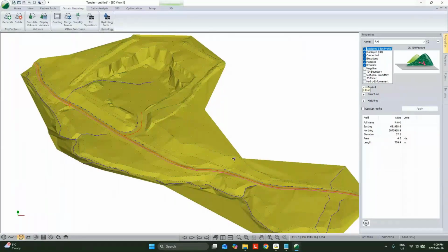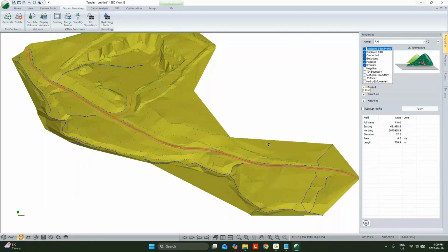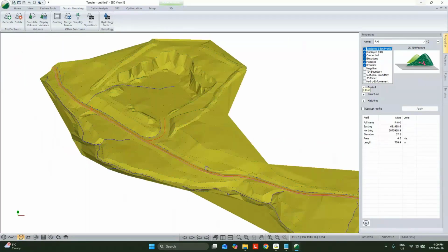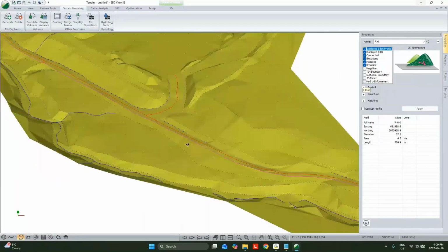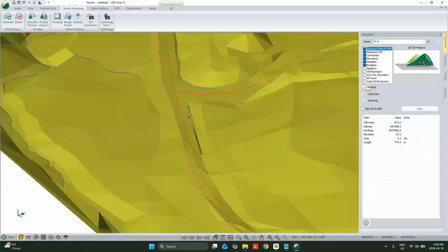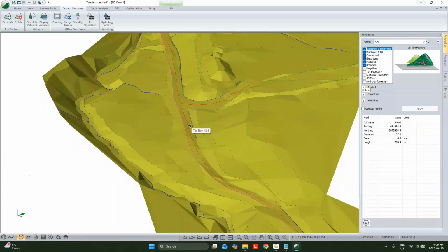One, we could totally just dump this right into LiDAR data and we'd have lines with the same information. Now, oftentimes that's not desirable. It gets a little funky, particularly in things like our ditches. The LiDAR data may have points here that are just poorly classified points. It might be a bush got coded as ground instead. So usually if we're combining our LiDAR data sets and we have something that's a full surface survey, we want